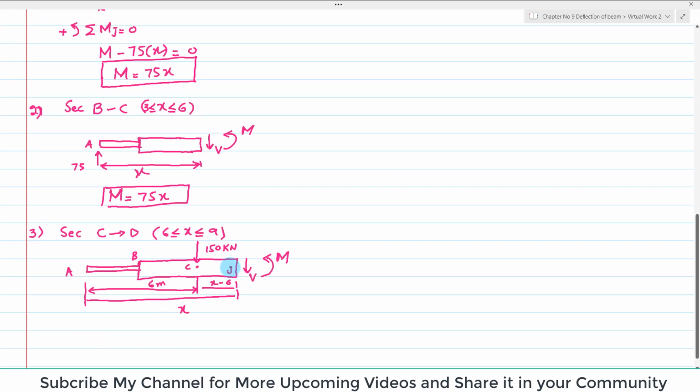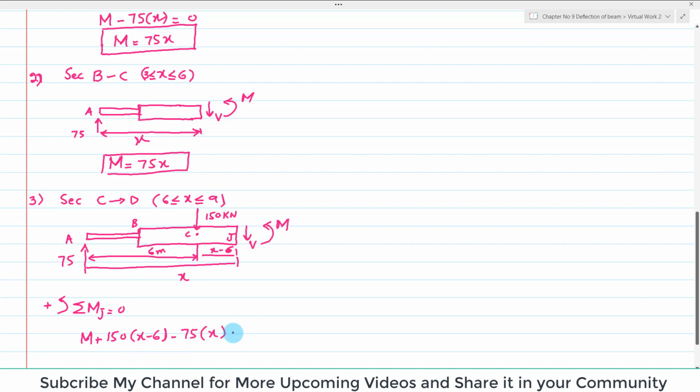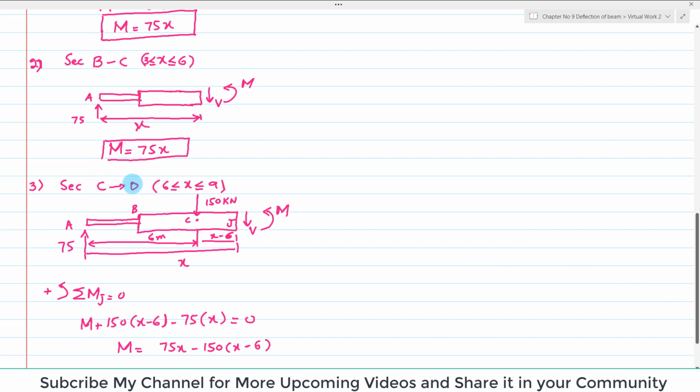So you can see, let this point be point J. So sum of all moments about point J is equal to 0, taking the counterclockwise as positive. So you can see there are two forces. One is this 75 at point A and one is 150. They are producing moment about point J. And there is a reaction moment again at point J, and this will be positive because it is counterclockwise. Now this force is also producing a counterclockwise moment. So 150 into x minus 6, because this distance is x minus 6. This force is producing clockwise, and it will be minus 75 into perpendicular distance x. Their sum must be equal to 0. So when you solve it, M will be equal to 75x minus 150 into x minus 6. So this is the equation of bending moment for the portion C to D.